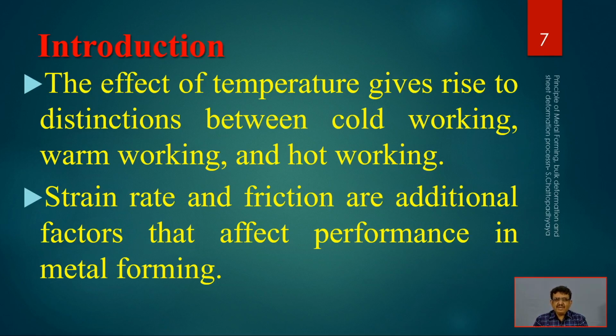In case of fluids, we are very much interested in strain rate. In case of fluid, the stress is proportional to strain rate, and the proportionality constant is viscosity. But here the metal is not a fluid, but whenever it is plastically deformable, fluid-like properties are there, and that is why fluid-like parameters are also taken into consideration.